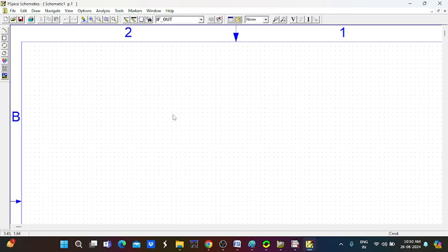Now the concept is present in the truth table. From this truth table we can make a K-map, and after K-map simplification we find the result. So that result is: the sum expression is A XOR B and the carry expression is A into B.